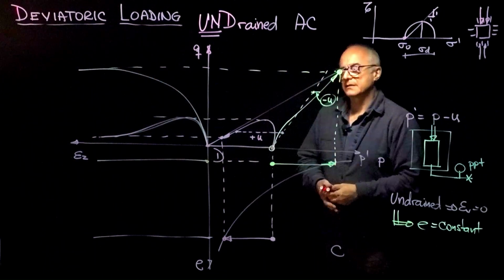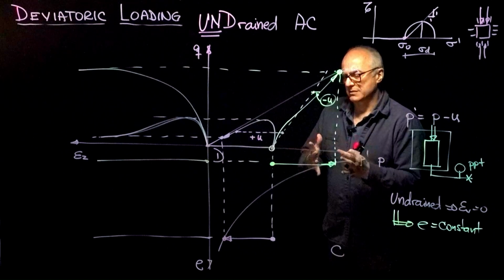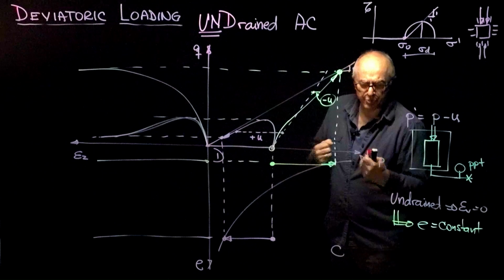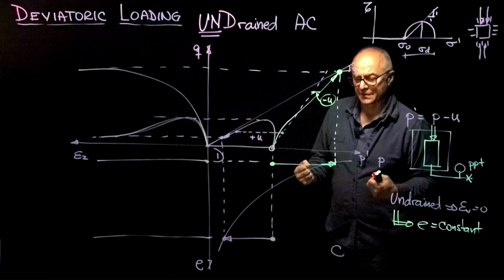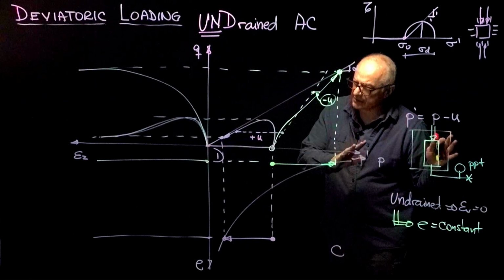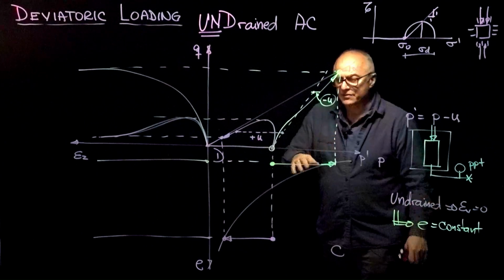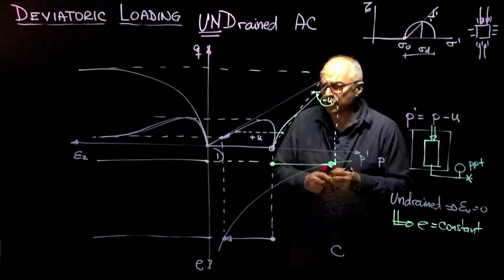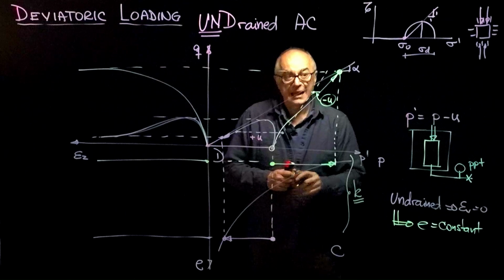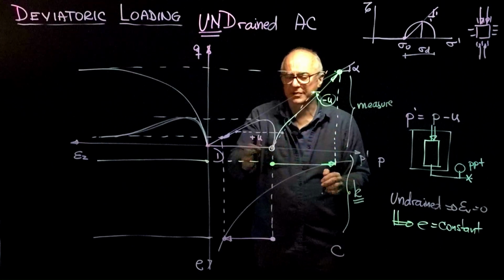Summary. The undrained behavior is totally matched and a consequence of the drained behavior, but it captures the coupling between the pore fluid and the granular skeleton. If it is undrained shear, it will shear at constant volume in that extreme case of perfectly rigid mineral and perfectly rigid liquid, water. And so we do know where the soil will encounter the failure line. So this is what we know. And we will have to measure the pore pressure to see how P prime is evolving.